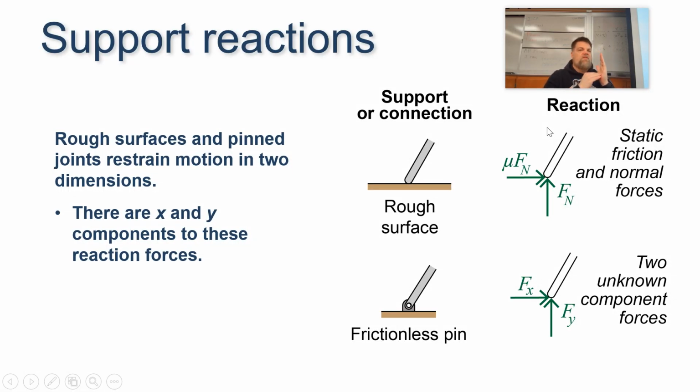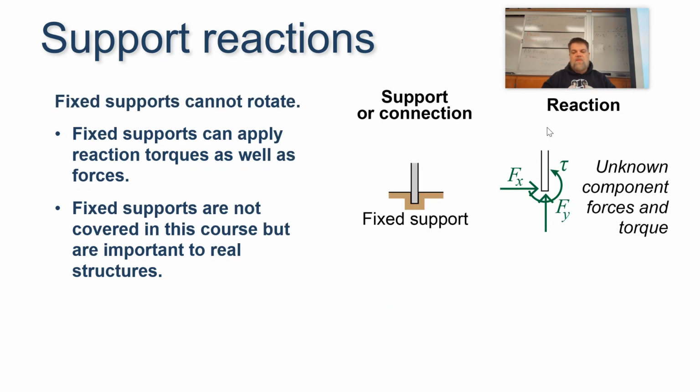These are reactionary forces. So if I'm pulling from a wall this way, that means that I'm pulling from the wall this way, which means there has to be a force that's going in the opposite direction because these structures don't move. So we have to balance. In other words, if you add up all the x direction forces, that equals 0. If you add up all the y direction forces, that equals 0. And if there's torque and you add up all the torques, they have to equal 0 because the object isn't going to move. We don't want it to move. That's basically what it's saying.